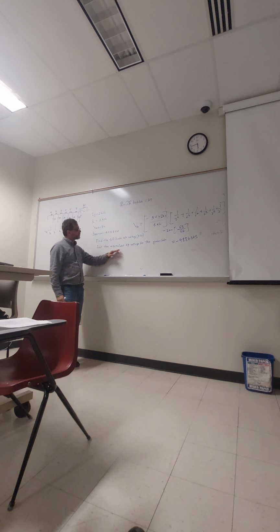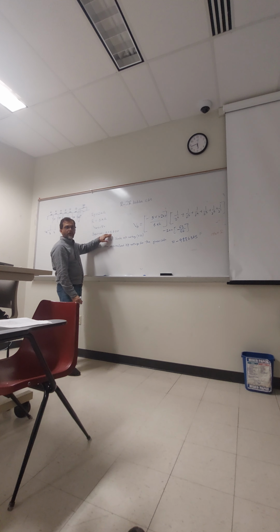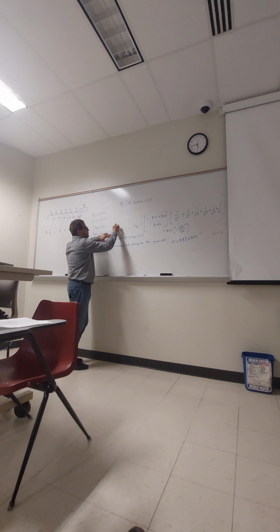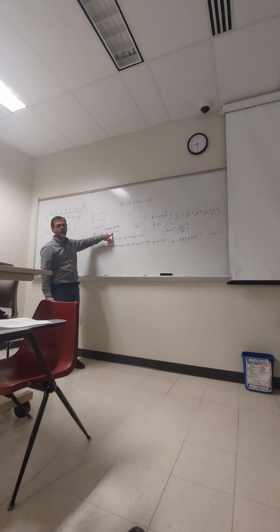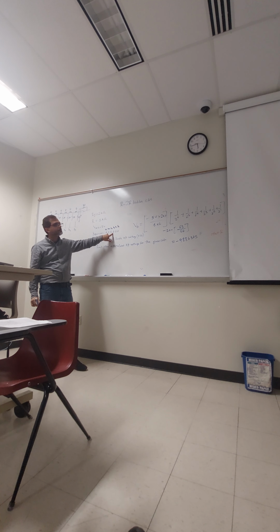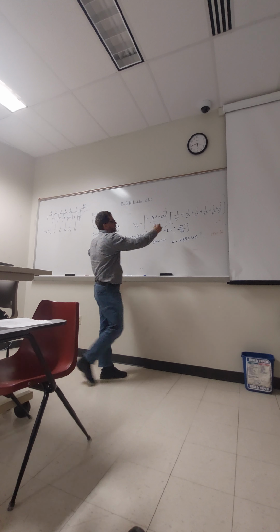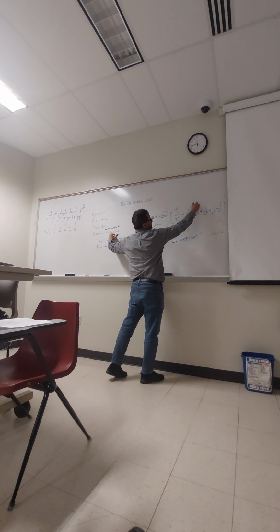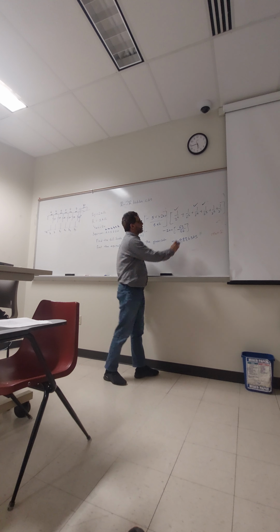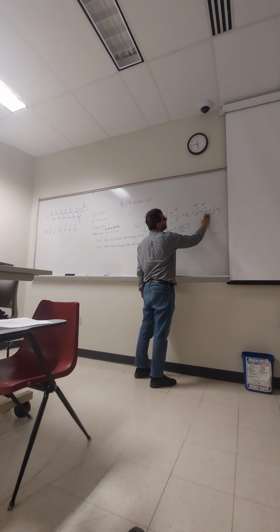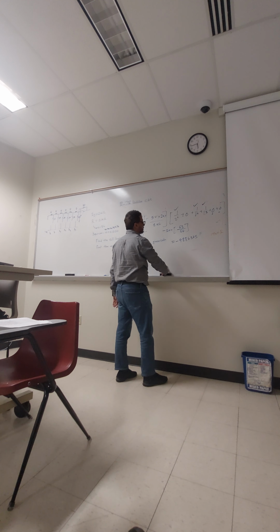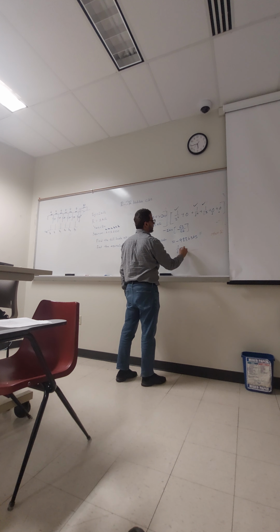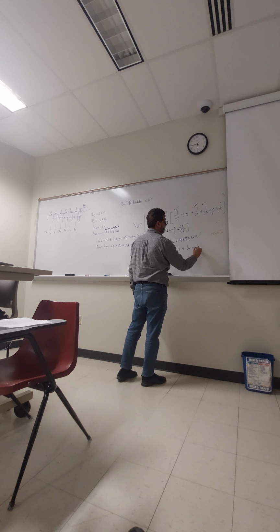Now if you have to find the equivalent output voltage for this one, right? So this is B0, B1, B2, B3, B4, B5. So you can see only B5, B3 and B2 are connected to the reference voltage, right? So which one will be connected? This one, then this one, and this one, right? So this will be 0. Sorry, this will be 0. This will be 0. So we'll have 1 over 2 to the power 1 plus 1 over 2 to the power 3 plus 1 over 2 to the power 4.